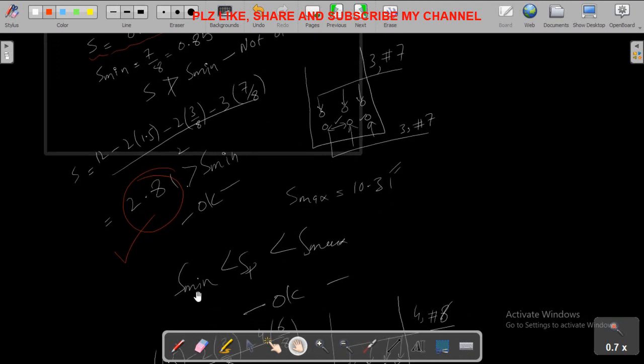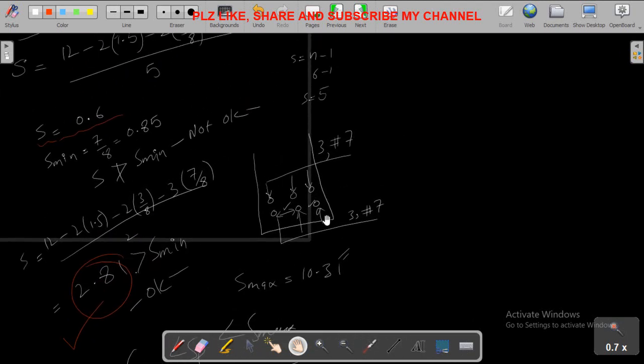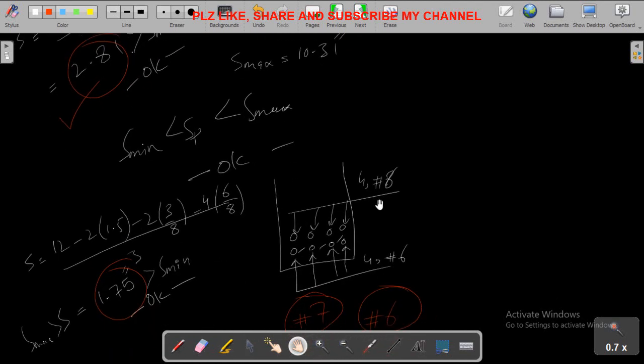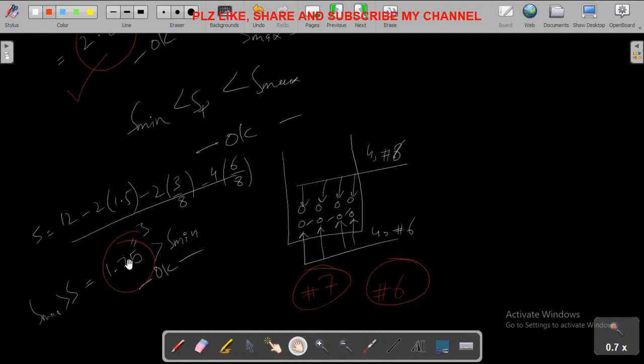So that's why SP is greater than S minimum, and I have already discussed this, and this is my final arrangement. You can see here 3 number 7 bar in top and 3 number 7 in bottom. Similarly, if you are using number 6 bar, so 4 number 6 bar in the top while 4 number 6 in the bottom, and it will give us the clear spacing amongst the bar is 1.75.